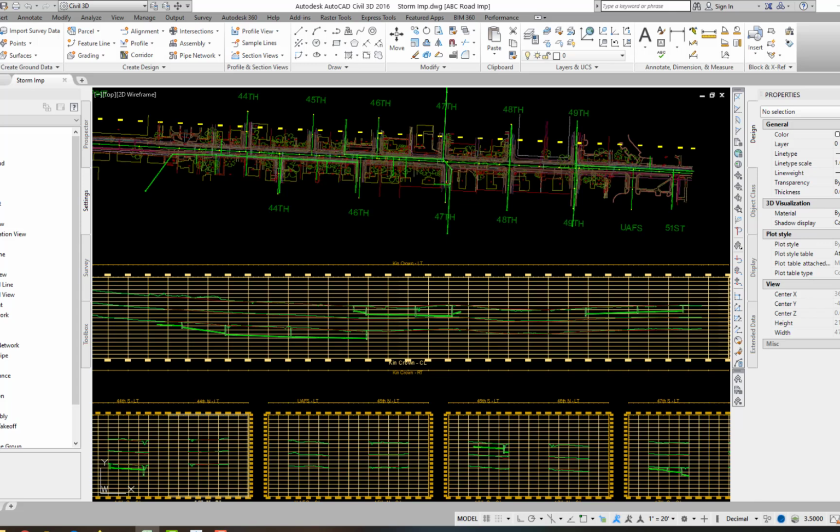When a structure is encountered that has a branch pipe connection thereto, the structure itself would not be initially numbered. The numbering would continue from the most upstream structure of the branch and proceed downstream to the main run connecting structure, at which time the structure would be numbered. The numbering would then proceed downstream along the main pipe run. A downstream structure would always have a higher number than an upstream structure, whether along a main or branch run.